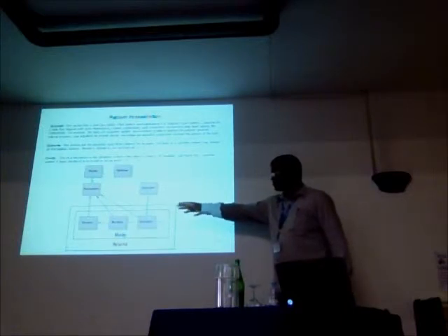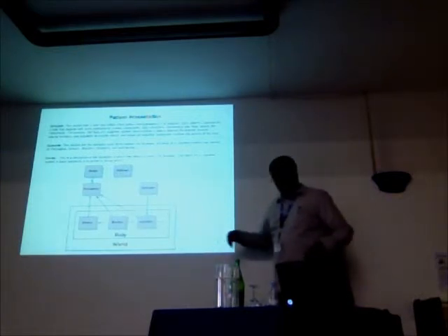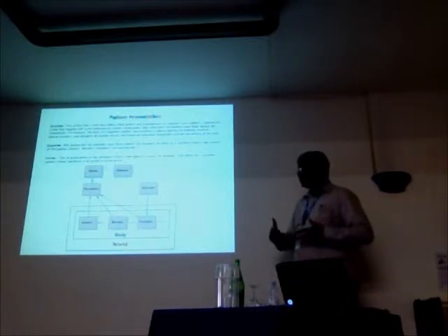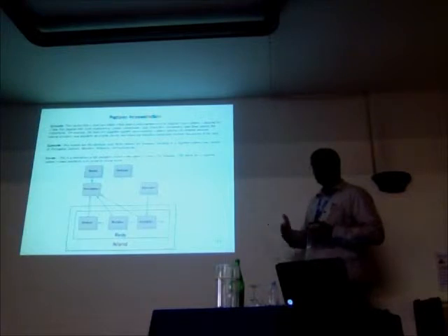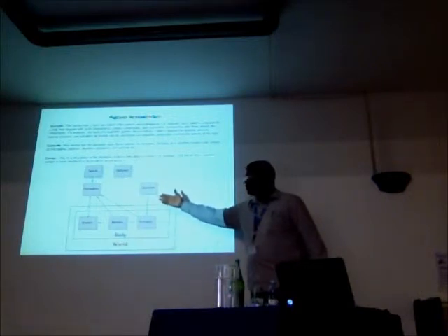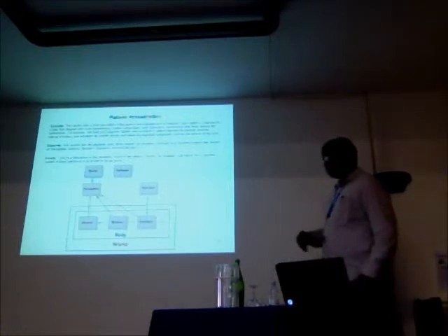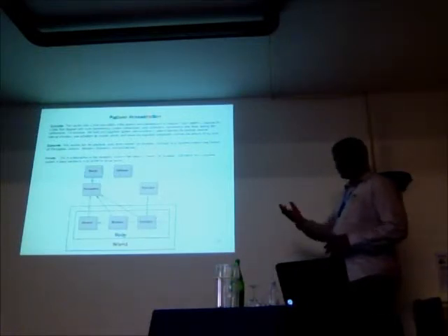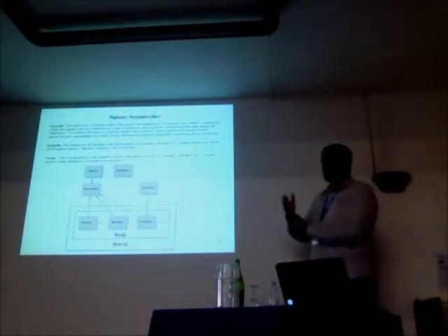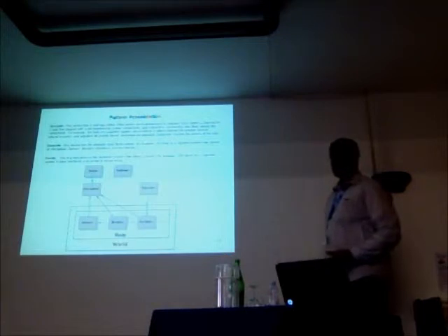has sensors, which take information, take stimuli from the external world. You have monitors which look internally at the body and will present stimuli to perception, but it's internal as opposed to external. And then you have actuators which act upon the world and then give some kind of result as to the state of the action that had been taken, as to whether or not the action succeeded. So, for example, if you have a robot arm that is attempting to move forward, you send a signal from the executor to move the arm, but it's blocked by something, then you have a failure because the arm couldn't extend as was desired.